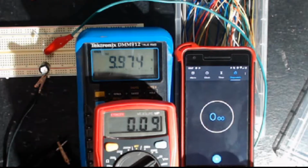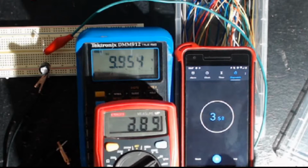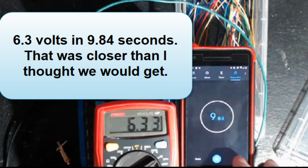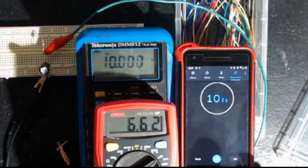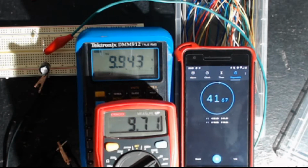In this circuit, I have the same values of capacitor and resistor. I have one meter measuring the supply voltage and another meter measuring what's across the capacitor. As the capacitor charges, I'll hit pause when I get close to 10 seconds. It looks like it's pretty close. At 9.8 seconds, I had 6.3 volts. Now we're going to go ahead and let it go and see what happens when we get to 50 seconds. We'll stop it again. Now here it's not quite as close. There's a little bit more of an error, which is really what I would expect to see. I would not expect to see perfect results.